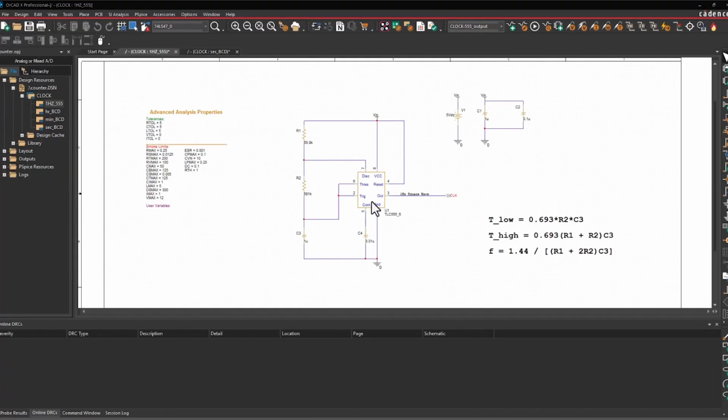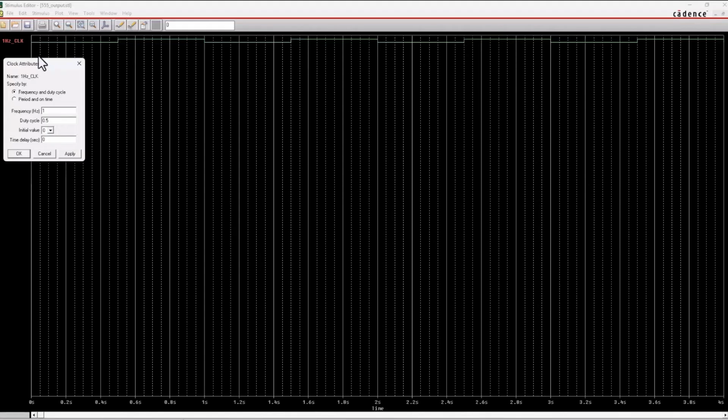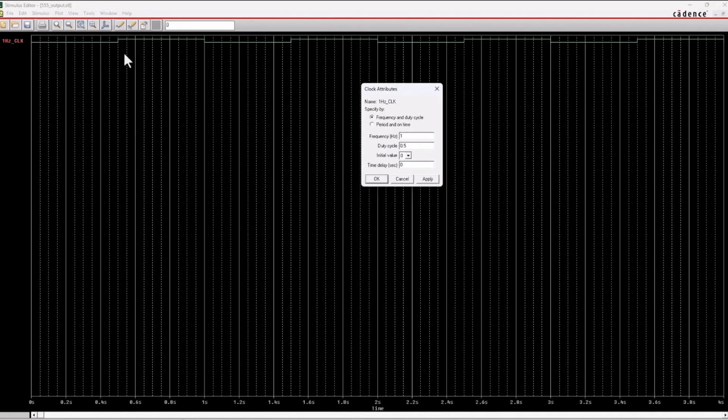So here's my clock output that I know is going to work without having to connect it to a breadboard or an oscilloscope. This will be fed into the rest of my circuit. And for the rest of the simulation that I did with the counters, I added a digital stimulus for my clock. I came into the editor and set the values that will be coming out of the 555 timer. This will all be digital readings in PSpice now. Realistically, this will be a 5-volt output.